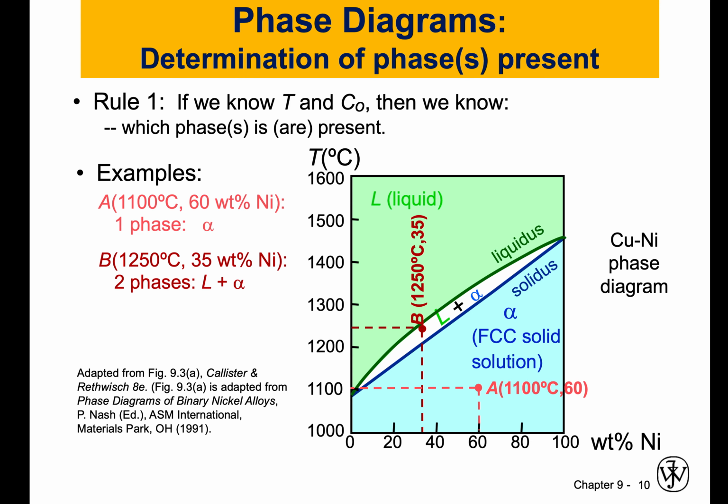So this is one of the applications for the phase diagram, and it's a good application, and we're going to show you more and more applications about how we can use the phase diagram in our analysis and in understanding how to create material. So if you want to create a material that is solid, an alloy that is solid from these two elements, if you have 60% nickel and 40% copper, you better be below the 1100. So you better be in that region, depending on what temperatures, pressure and concentration you're using.